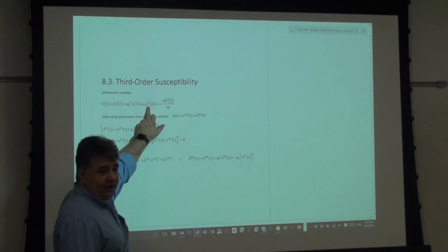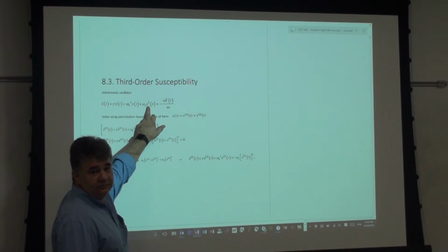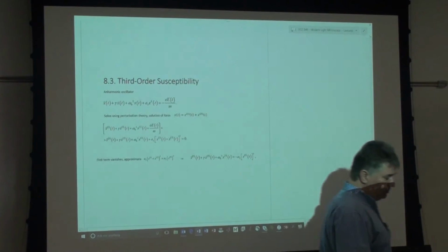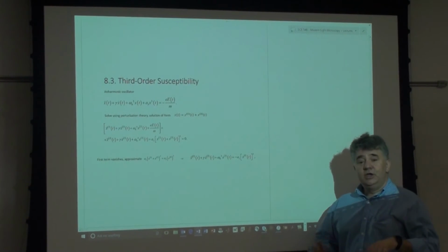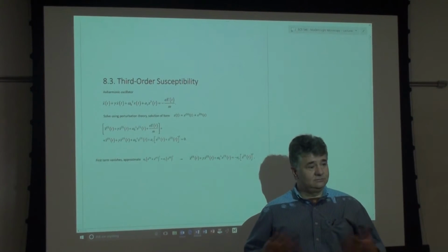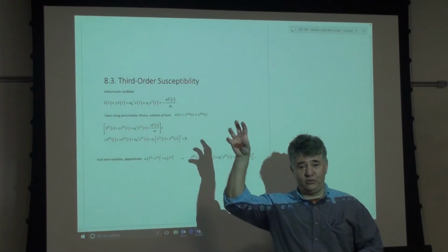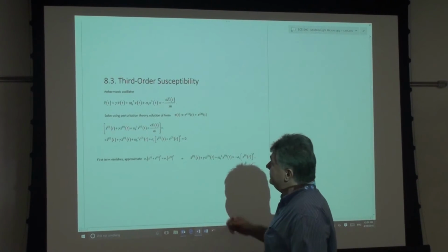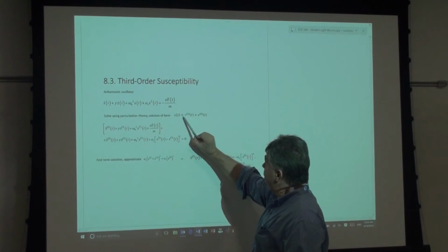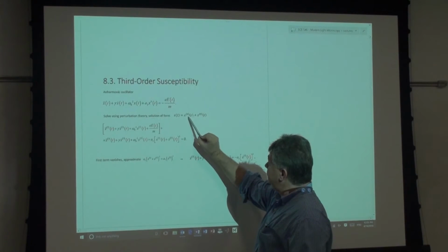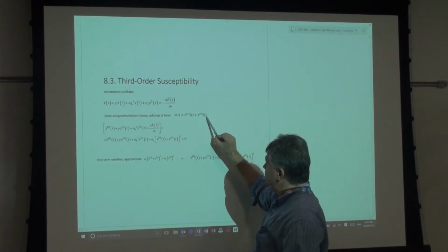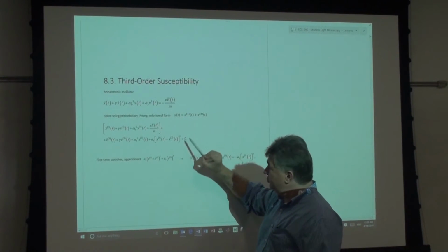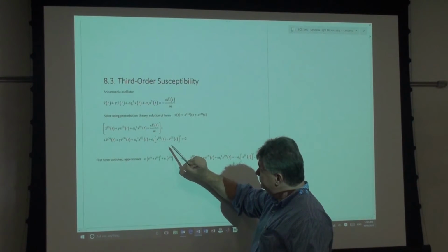force here is actually of third order in displacement. Everything, the procedure we established, will work the same way. It gets a little messier, because you'll have to power 3 now, you have many more terms. Well, let's take a look at it. So again, I'm going to make my total displacement x as x1 plus x3. I'm going to neglect all the x3s in the driving force like before.